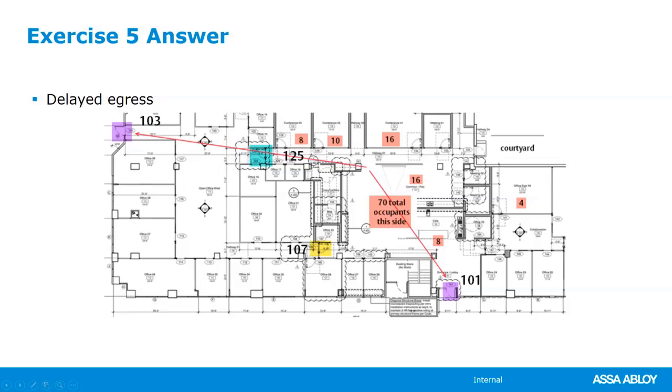The best solution would be for the owner to add another exit door from this side of the building over off of this hallway to the outside. And then this is no longer an exit access door. Then you could lock it with any solution. But sometimes an architect will have a drawing and your exit access through the door leads to another exit and is a required means of egress.